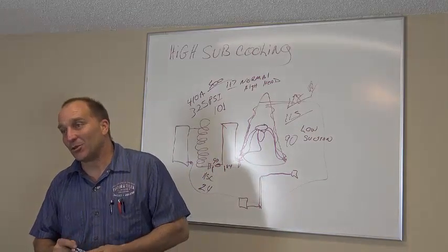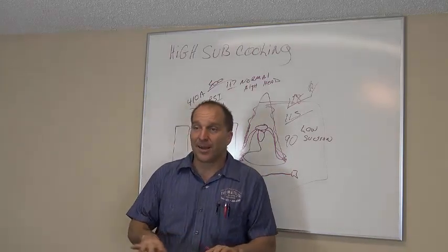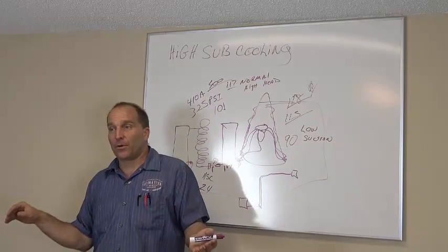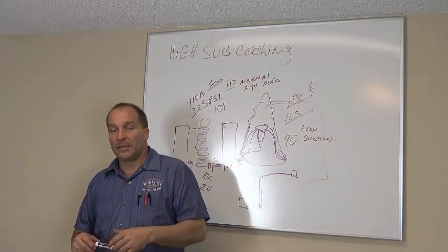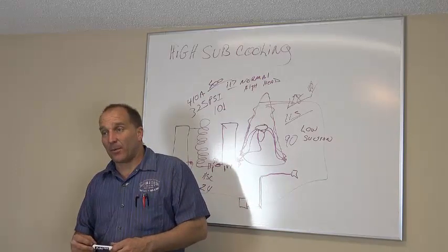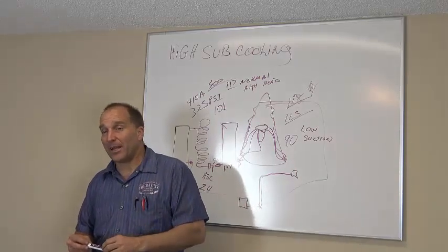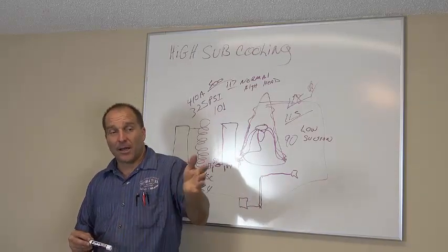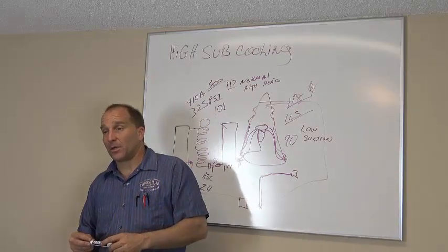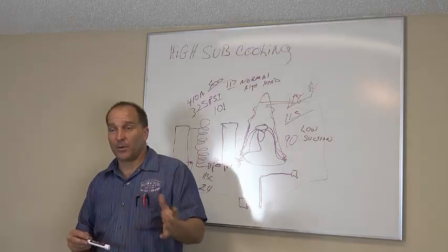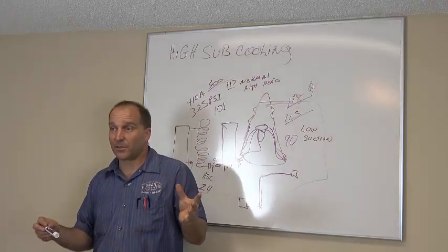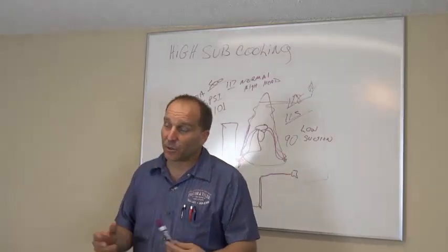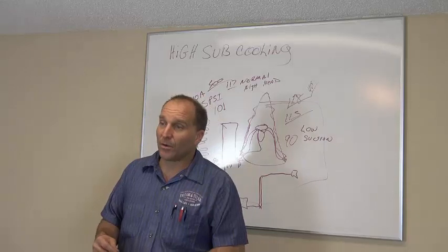So what you should have done was check the entire system first, right? And tell him you've got a dirty evaporator coil and a dirty condenser coil. Very possible when I clean this evaporator coil, I don't know how much damage is done to your compressor, so I don't know how long it's going to last. I don't know how long your condenser fan motor is going to last, simply because you've been running this system for the last 5 or 6 years, and those bearings have gotten really hot, so if I clean this condenser, it's possible your fan motor will go out on you.